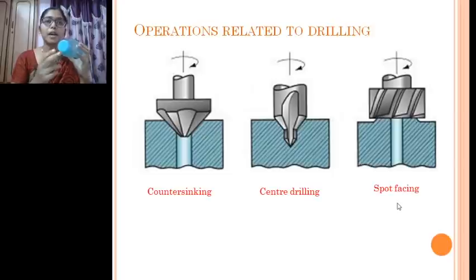Center drilling is the operation done to locate the center of the workpiece. So while holding longer workpieces on a lathe machine, initially the center drilling is done to locate the center.